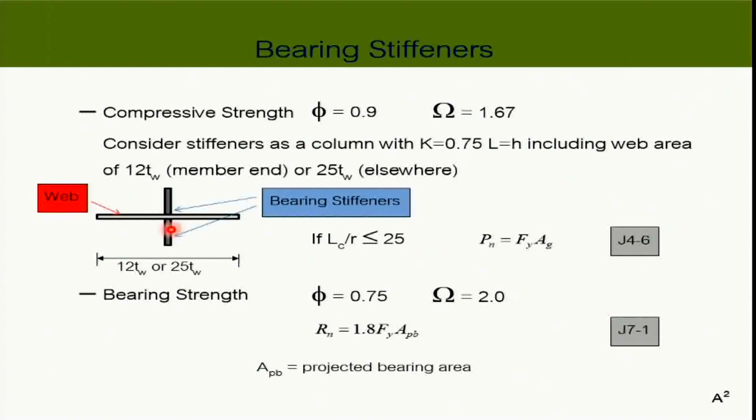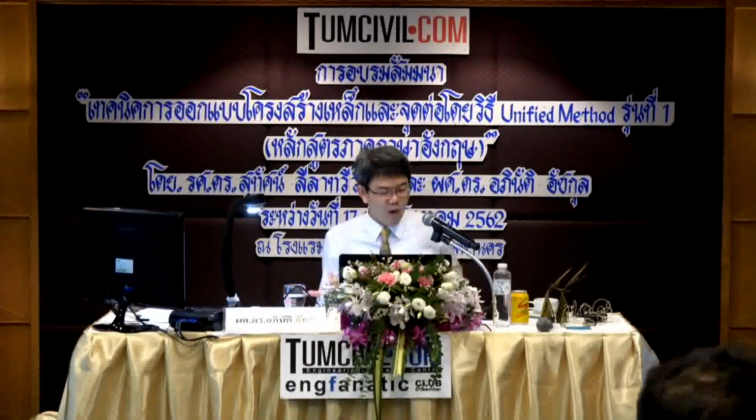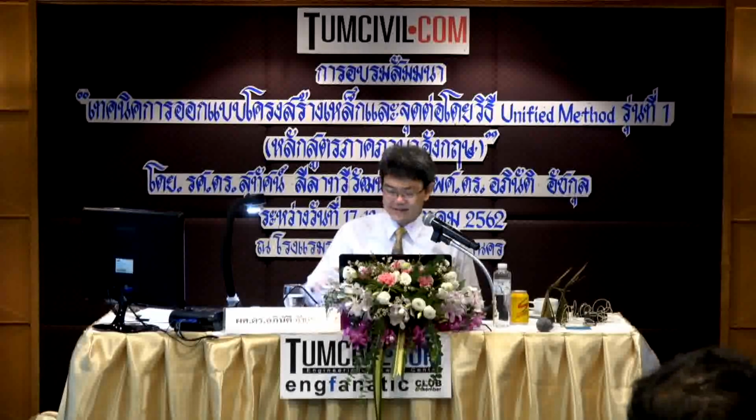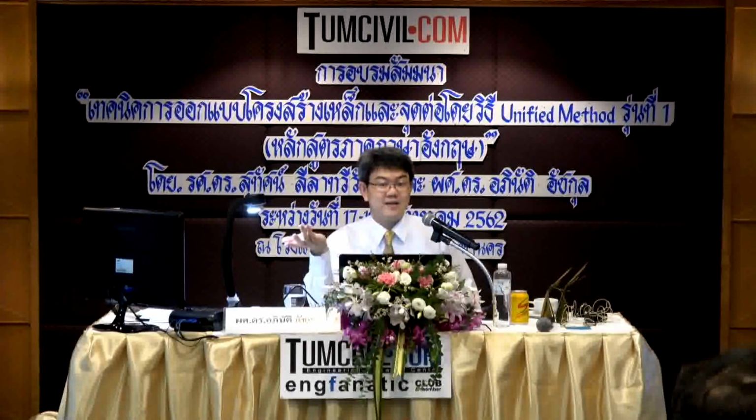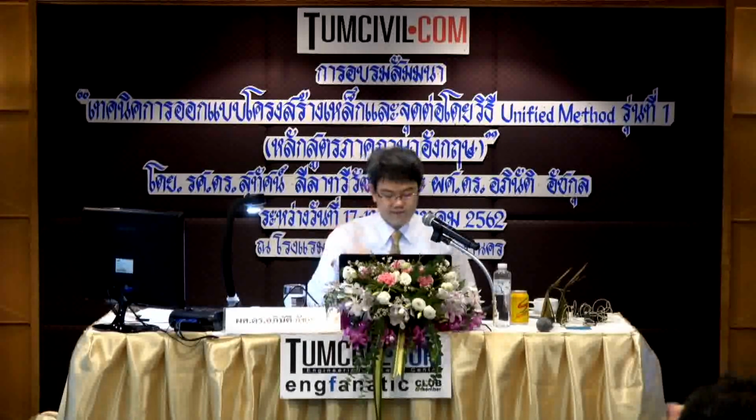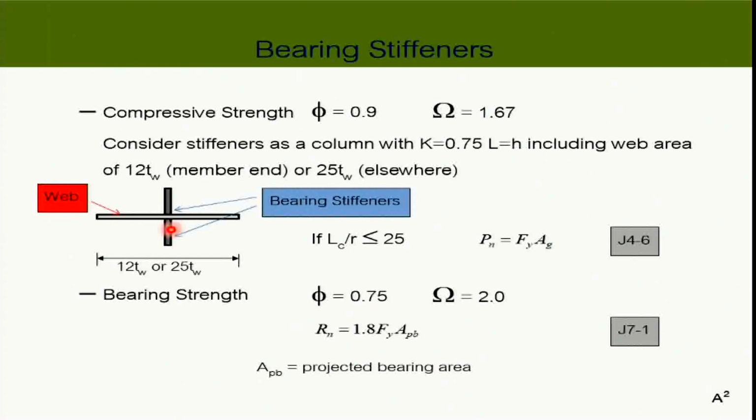But if you don't want to go home, you just need to calculate this and see if your beam can survive the point load. If it can, you don't need bearing stiffeners. If it cannot, you need to design bearing stiffeners. And I generally calculate that, and for the beams, I don't use bearing stiffeners. And I remember the fabricator asked, "Are you sure?"